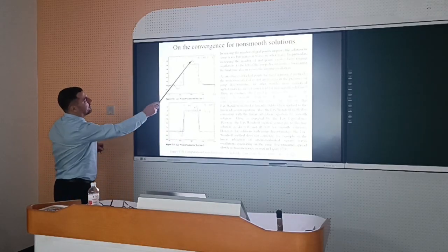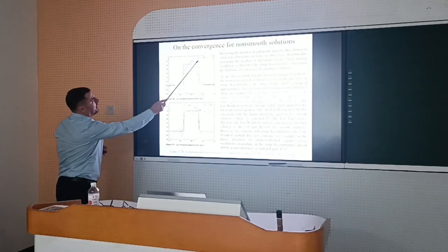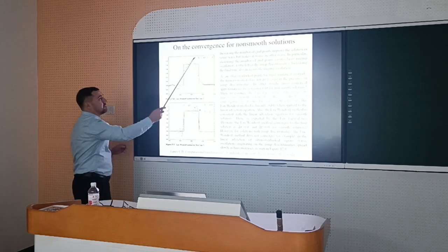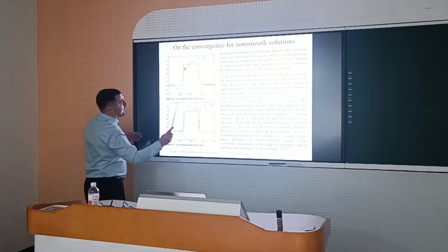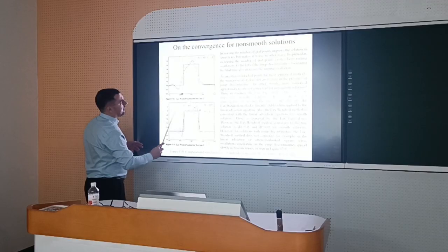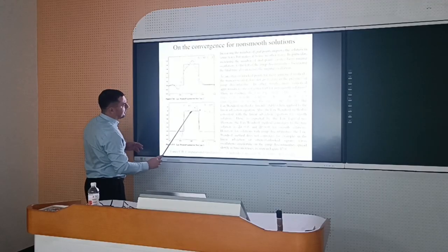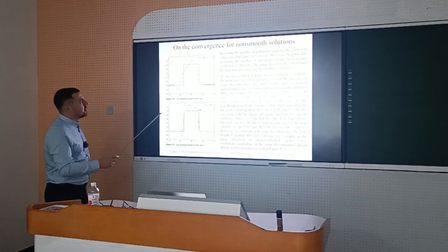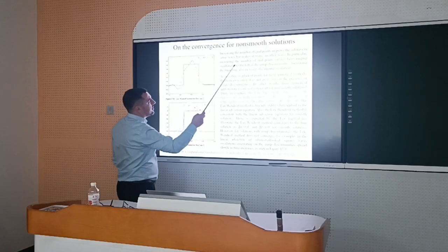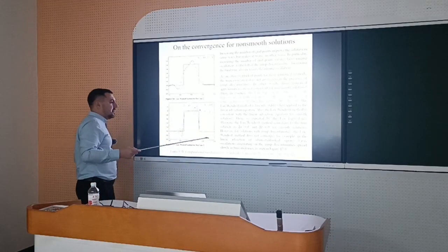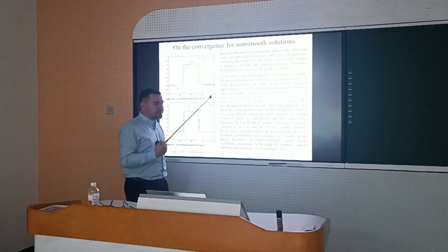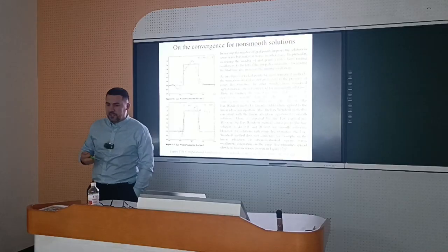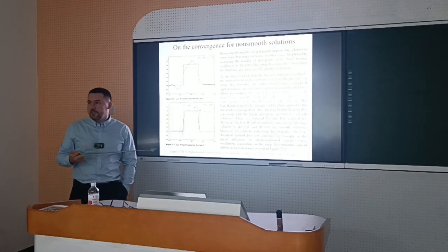And he checked different resolutions. So here n equals 40, and here n equals 600, and he checked different times. For example, the wavefront propagated from left to right several times, and 40 times, so many times. And he compared the numerical results. Increasing the number of grid points improves the solution in some ways, but makes it worse in others. The problem is that when you have discontinuous solutions, an increase in the number of grid points does not necessarily improve your numerical solution, and that's very bad.